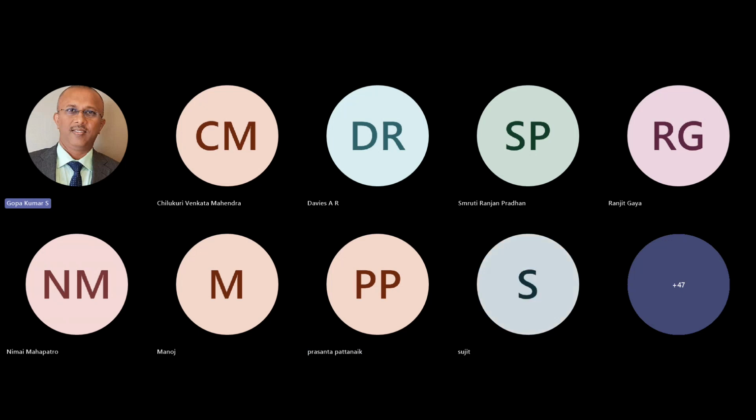Yeah, so the best way is to make a TNS system or TNCS system. That means there is a separate neutral and a separate protective conductor, so fault return will happen through the metallic fault return path. The best way is, as Mr. Smriti asked, from the consumer premises to the transformer neutral point, there has to be a metallic fault return path, maybe a fifth conductor. You can also use the fourth conductor, that means neutral, but then it needs a lot of discussion. A metallic fault return path only will ensure that the OCPDs are tripping within the time. That is very important. Correct.